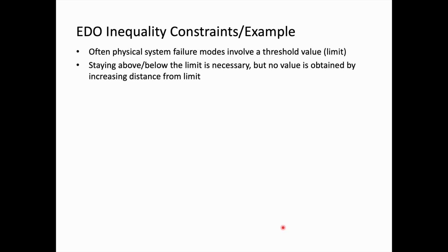Well, what's the effect of that? That reduces the stress, but it's going to increase the mass of the system. It's probably going to increase the cost of the system. But did it help anything? It really depends on what the objective function is. But if increasing the mass did not help the objective function, then there's really no value to reducing the stress a fair amount below the stress limit.